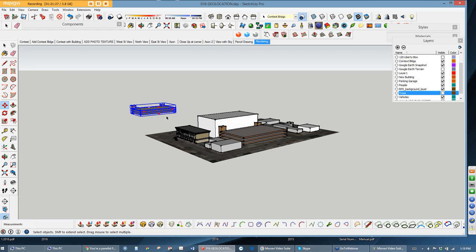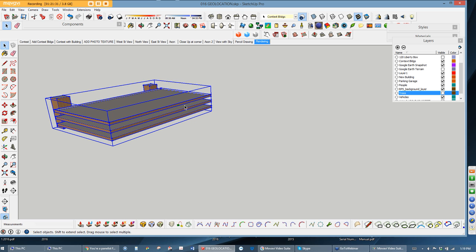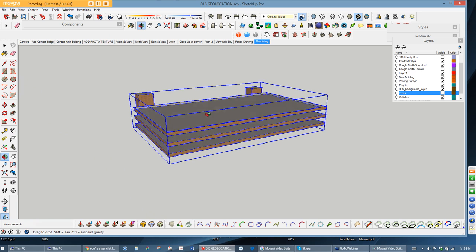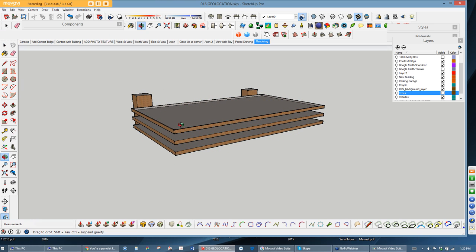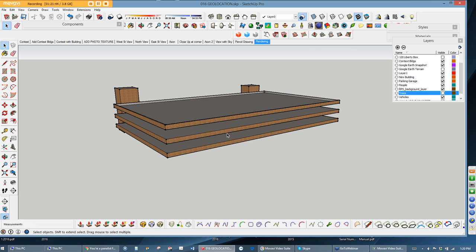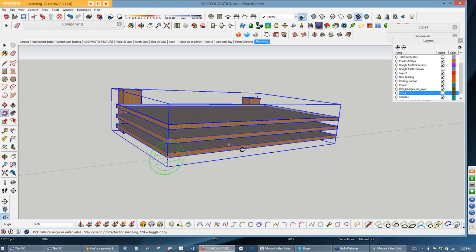We'll just take this one. Now, I don't know if you want the whole parking lot sloped or not, but initially you could draw the parking lot all by itself, just out in space. So build the structure first. Don't worry about the slope. If you're worried about slope, then you may have to start building this at a little bit more angle. I'm going to pretend there's some slope here. I would just rotate this. Use the rotate tool and grab this and tilt it.